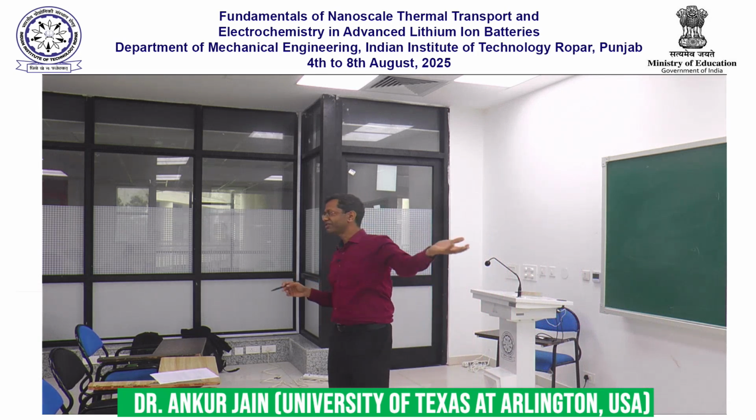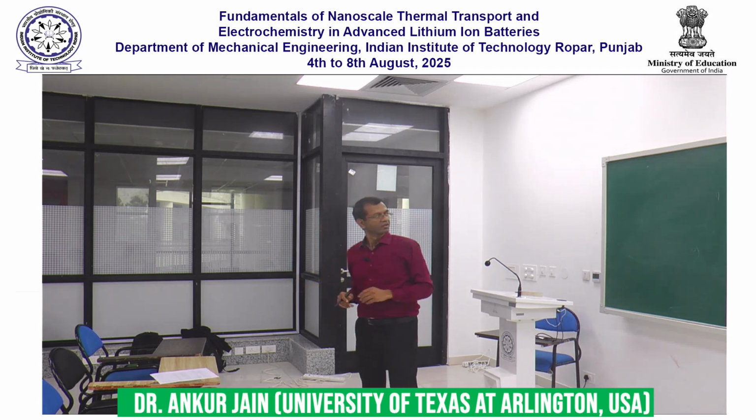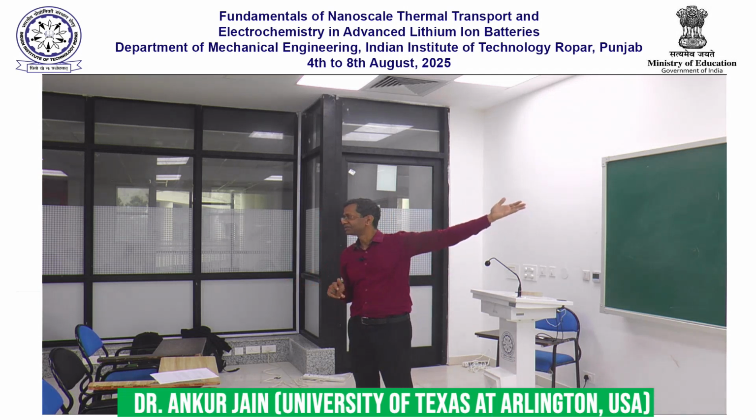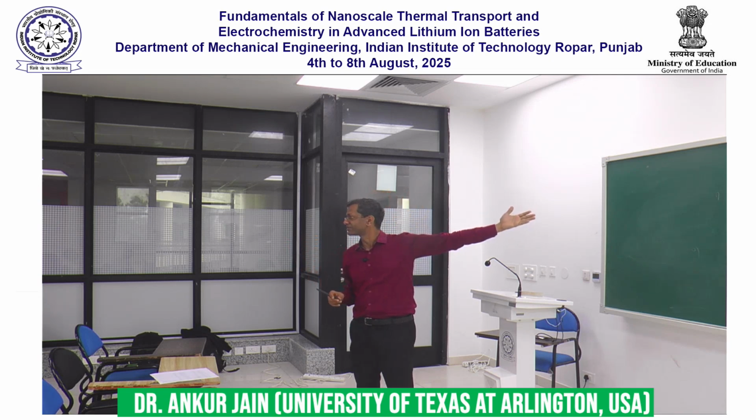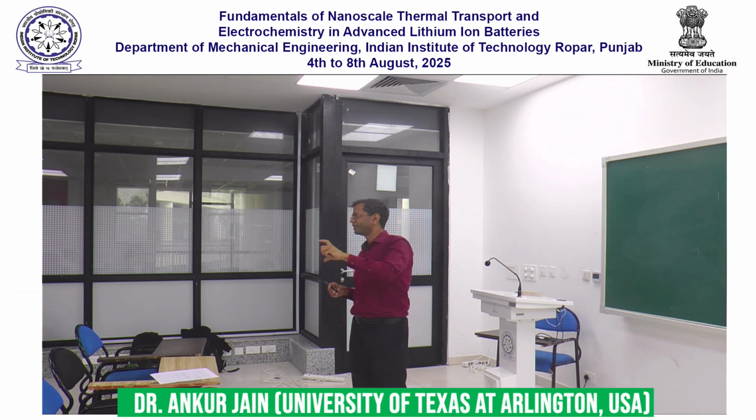Now the battery engineer comes and says, you know what? This is a very small cell. This is typically the cell that goes inside a cell phone, right? And that is the reason why the battery inside the cell phone doesn't have a fan blowing air over it, right? Somebody maybe 20 years ago did very similar calculations for a cell phone and showed that look, the battery of a cell phone really does not need any cooling. If you just leave it there, it will cool down enough by itself.